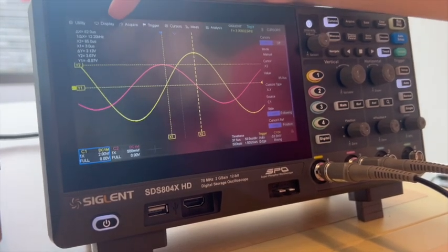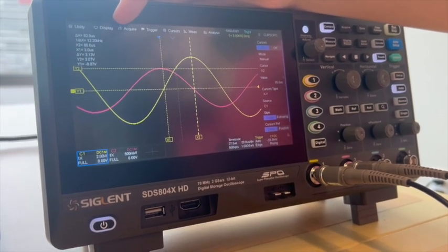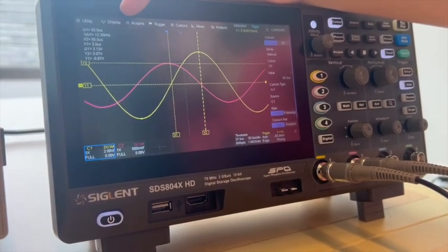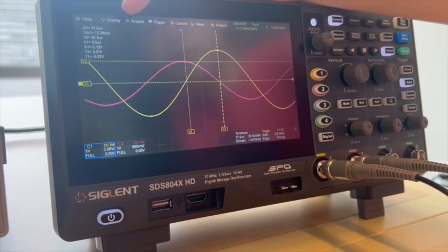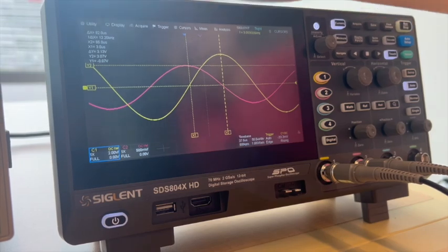Up here, you'll see our delta x. You want to pull that value. Now that you have delta x, you're given delta t by your frequency, and you have 360, you can now solve for your phase shift. So then running from there, you'll get your phase shift.